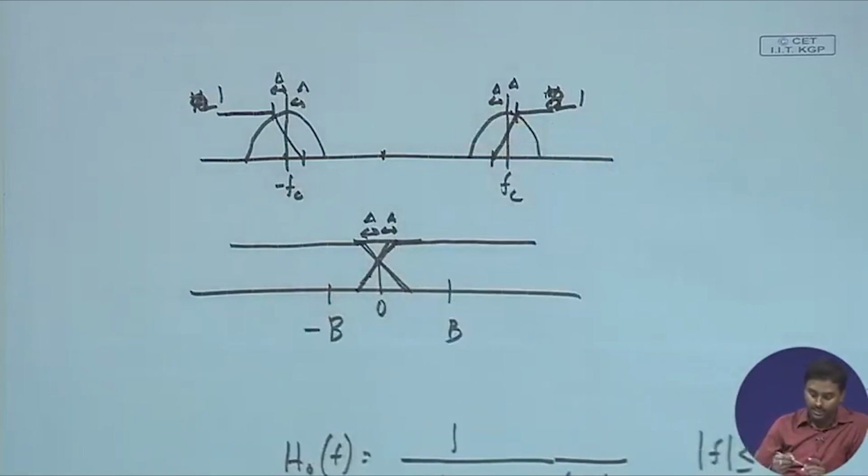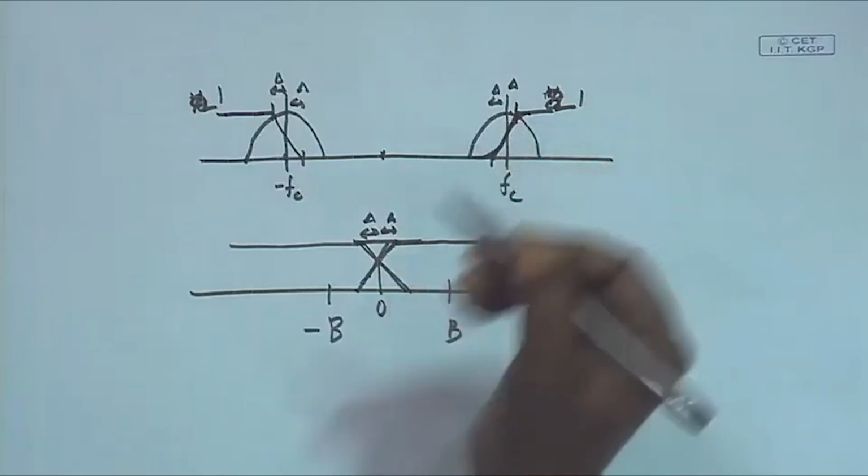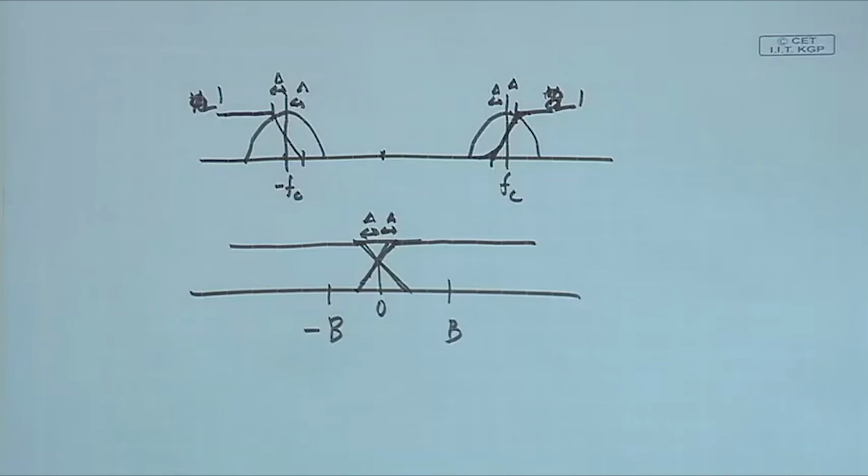So, now you can see that whatever relationship that we have got over here, I can actually have a realistic filter, okay, where there might be some roll off. Of course, it needs to be linear, or maybe some near linear part I can just select, and that will still suffice, okay. So, probably the filter will have some of this. That will create a little bit of distortion, but as long as the slope is almost tracking whatever I wish to do, it will almost give me a similar result, okay.